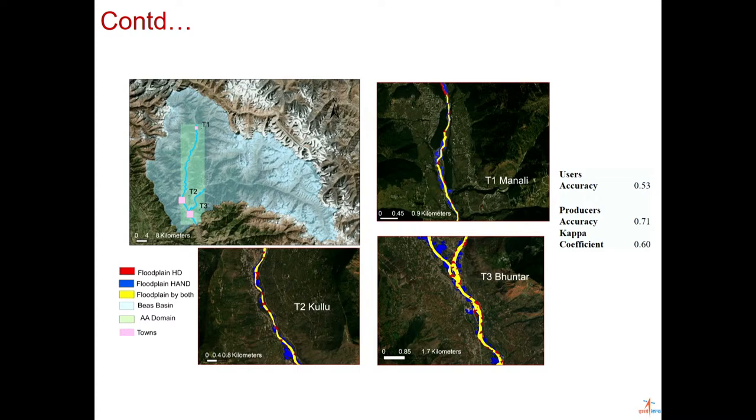So this is how, if you don't have any data set, you simply take a DEM. You already have the add-on of HAND. You just give the DEM value, and it asks you only for the DEM and the river network for which you want to generate the floodplain map, and then you can generate floodplain maps using the HAND tool. So in this case study we tried to see which topographic index relatively better mimics the floodplain map, or the reference map, that we got using the hydrodynamic model. This is another application of the HD model that we try to address in this case study.